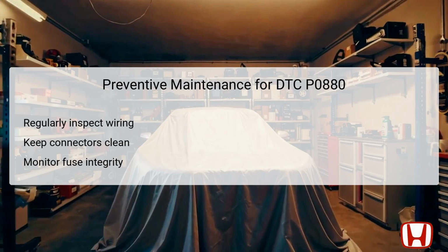P0880 in the future. Regularly inspecting the wiring and connections associated with the TCM can help identify potential problems before they escalate into more serious faults. Keeping connectors clean and free from corrosion is essential, as contamination can lead to poor electrical connections and signal disruptions.